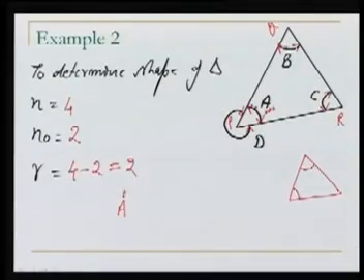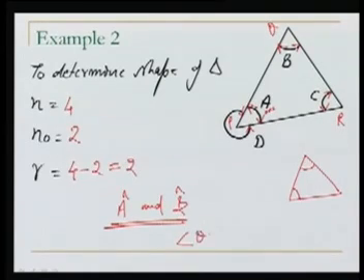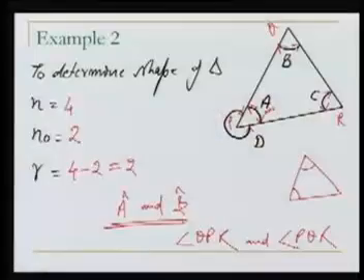Now the important thing here, what is desired? In order to know the shape of the triangle, the desired things are A hat and B hat, that is, angle QPR and angle PQR. If you know these two, the third one can be determined, meaning the estimate of that. So these are our parameters here, 2 parameters. Now we will try to adjust this problem by 2 methods, the observation equation method and the condition equation method. First of all, we will do it by the observation equation method.